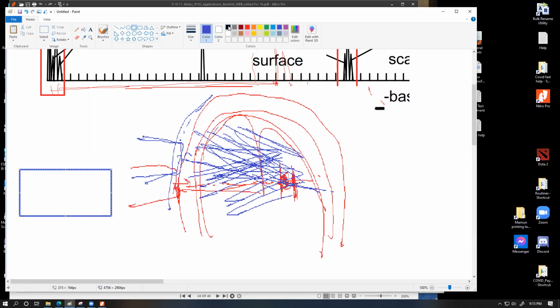In an actual probe, we usually don't have only one piezoelectric crystal. We have multiple piezoelectric crystals aimed in different directions. So let's say this is aiming in this direction, or this is aiming in a bit different direction. They can be either concave or convex, depending upon the device. And each of these individual crystals will send out slightly different frequency of ultrasound so that they would not overlap, and they will be detecting that exact frequency.